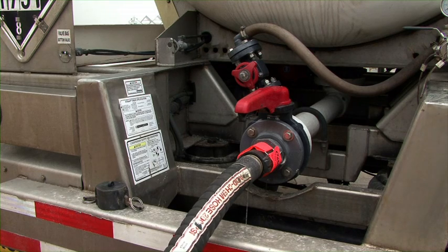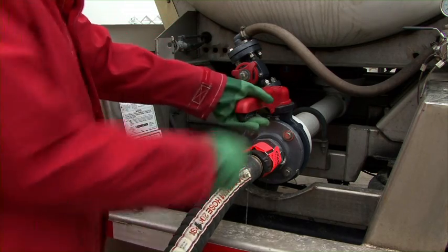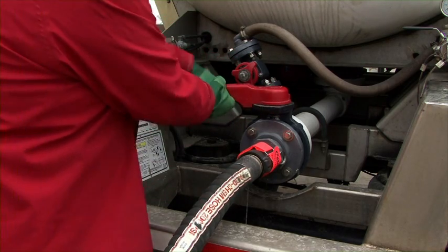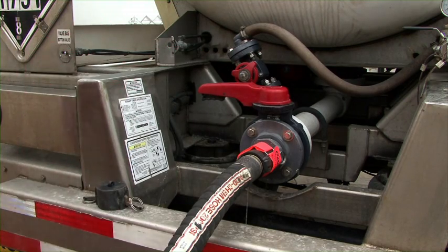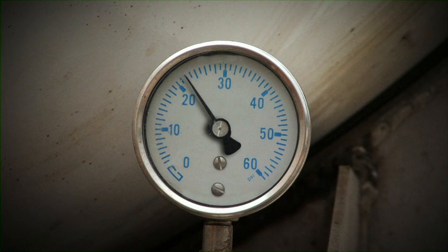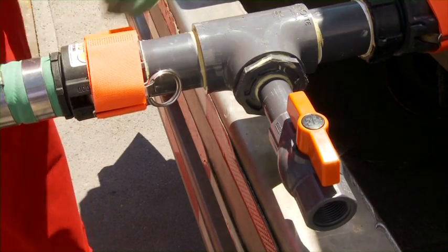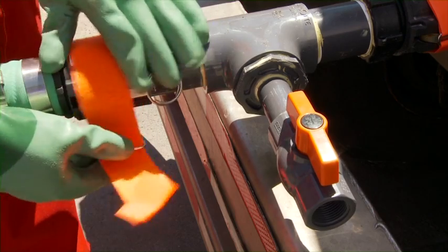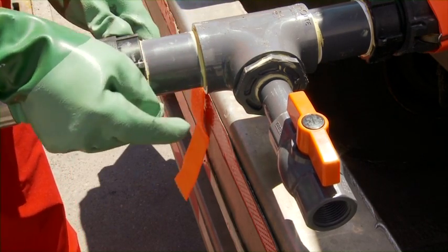Once the transfer has been completed, shut off the air supply or pump and close the unloading valve. Follow your company's procedures for disconnecting the delivery vehicle from the storage tanks. Consider both the potential air pressure and the residual liquid in the unloading lines. Vent and drain as required prior to disconnecting the hose. Disconnecting pressurized lines can be very dangerous to personnel in the area.